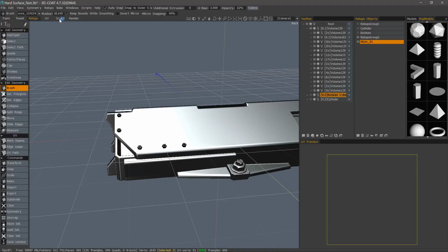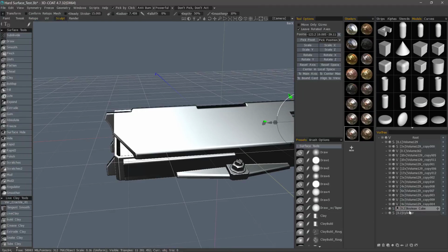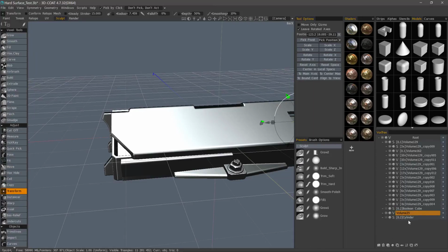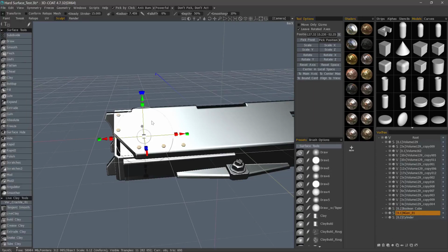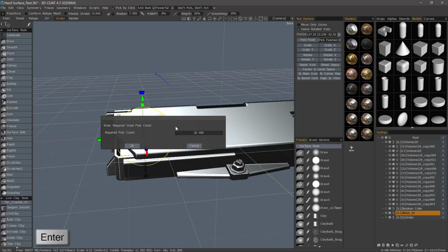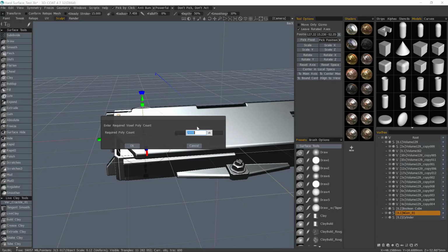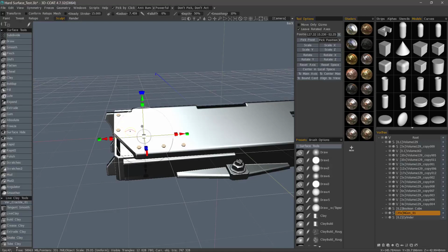Once more in the sculpt workspace, if I need, I can create copies of these as well. So I'll create a new layer and hit my hotkey. I'm going to increase the resolution, but just as you would in a typical 3D application, if you don't already have edge loop support around your hard edges, then it's going to smooth excessively. That's not what we want. I can get around that by hitting the enter key, and it's going to temporarily switch to voxels. It gives me the ability to select how dense I want this object to be. So let's go with maybe 750K. And then it switches me right back to surface mode.